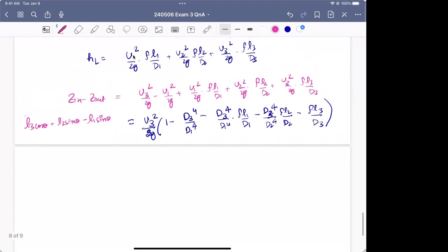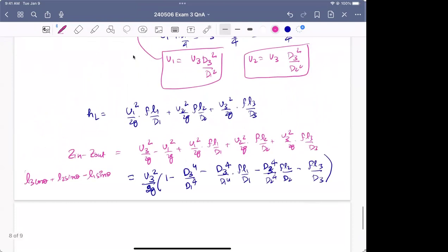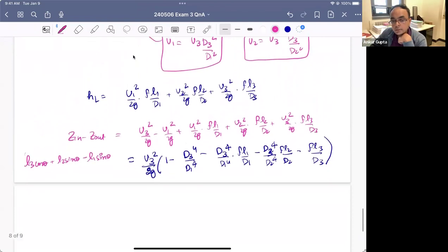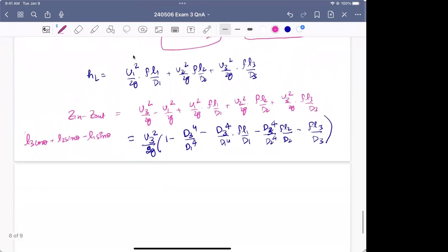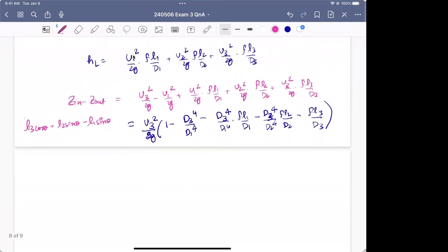Yeah, no, it's clear. But if for example, I have 4 pipes instead of 3, and there are minor losses and major losses, do I multiply according to the chart that's at the end of the practice exam? There is the flanged and threaded thing. Do I multiply the number of the pipe by KL and add them together?